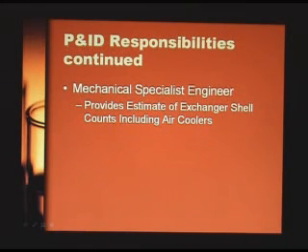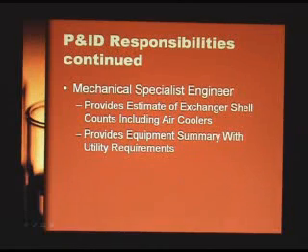If there is a service to cool or heat some fluid, they will say, okay, this can be done in one shell, or one shell will not be enough. There have to be 2 or 3 shells sometimes if it's a big process flow and big heat exchange. So they will provide this estimate, and provide an equipment summary with utility requirements.